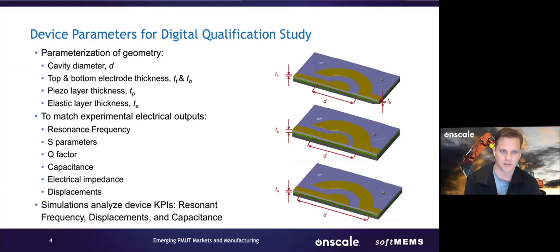The piezo layer thickness, of course, will impact performance, and the elastic layer thickness will impact performance. So the first step is to parameterize these geometric variables.